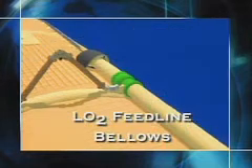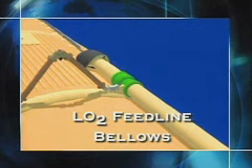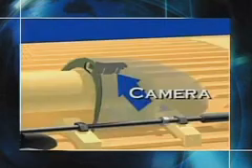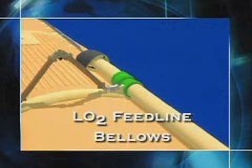The liquid oxygen feed line bellows: again, there are 5 bellows. 3 of the bellows are exposed. The other 2 are inside the inner tank. The purpose of these is to allow movement during tanking and also during ascent. We have added a drip lip to this to reshape the edge so that the condensate drips off rather than forming around that bellows area, which could be a debris source.